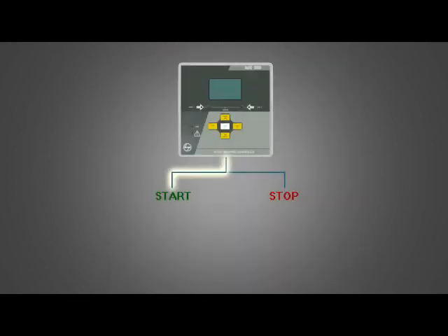When the output is active, the signal is high since it is set to normal. When the output is inactive and is in a normal mode, the activation creates a low to high signal. An option is also available in which output is high by default and activation leads to de-energizing of that output, which is a low to high signal.